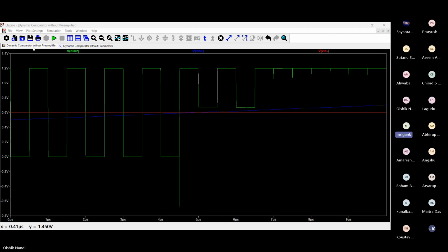So for very close inputs, the outputs become very close to each other, and it is a quasi-equilibrium state. Generally, in a circuit you will have some noise because of the devices themselves, and it will ultimately make it switch to another direction. Right now we are not simulating with any noise. I hope in the recorded NPTEL lectures you have been introduced to device noises, right? Every device contributes some thermal noise. Likewise, you may have supply noise sources. Because of those noises, ultimately it will settle to one of the values.